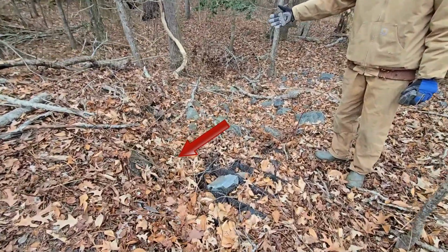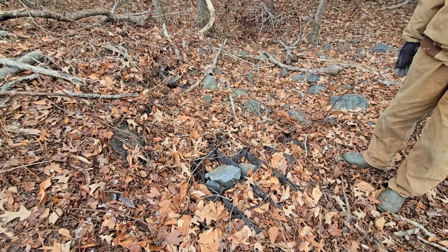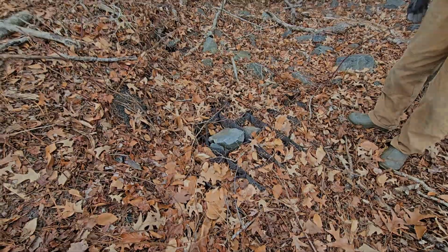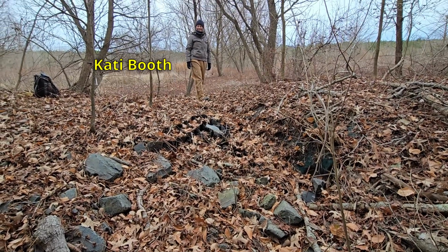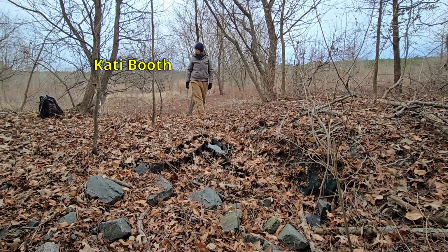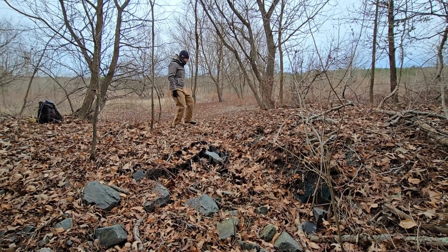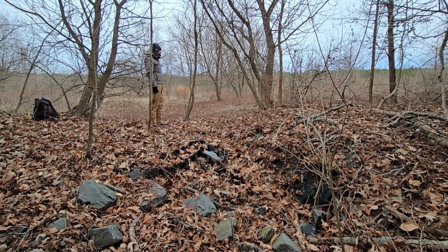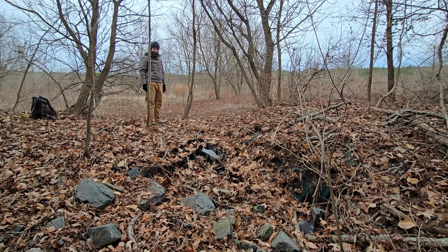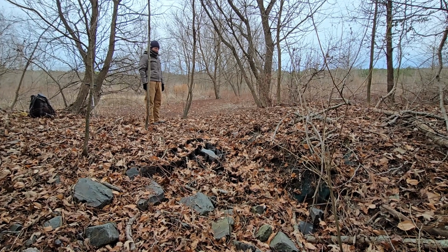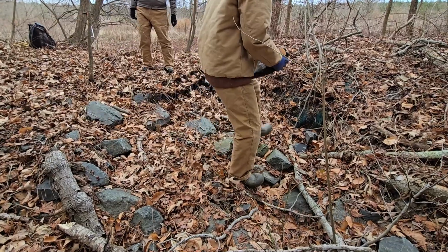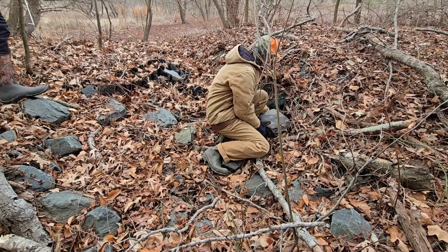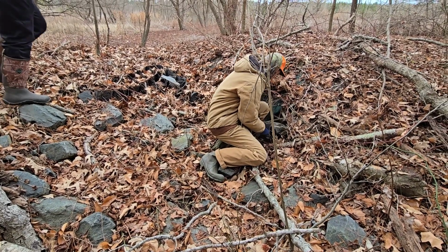We're seeing soil loss and erosion here, and you can see this honeycomb fabric structure, which was completely covered by soil at design. The spillway is eroding because it was built narrowly and carries water over a steep slope, which is the dam. Water in the spillway was not flowing over rock, and the rock was not embedded in the ground. Katie is standing on the crest of the spillway, which is in danger of washing out and will drain the entire wetland. We decided to repair the spillway by hand instead of going through all the paperwork and the delays associated with getting a contractor on site with heavy equipment to maintain the spillway.